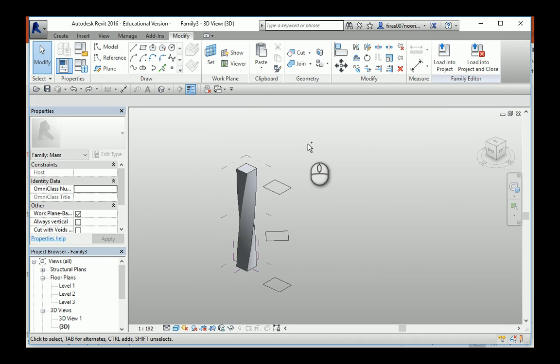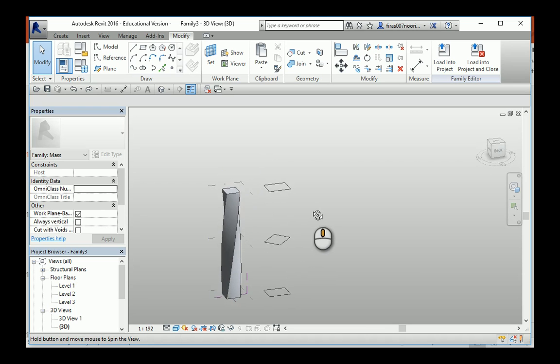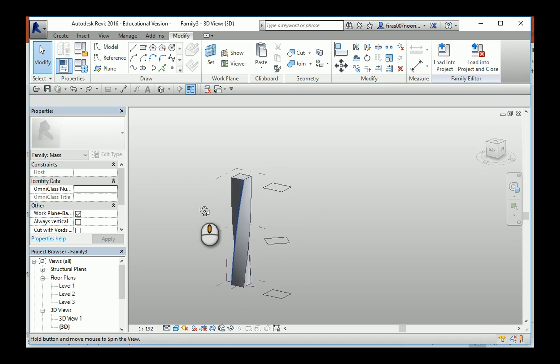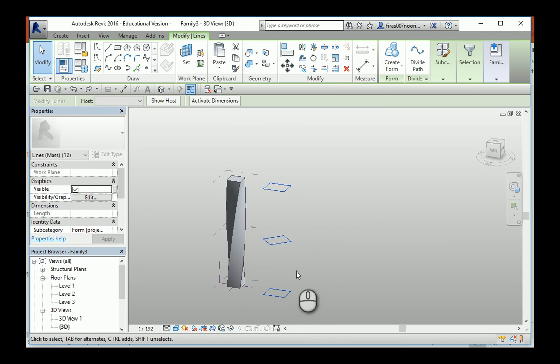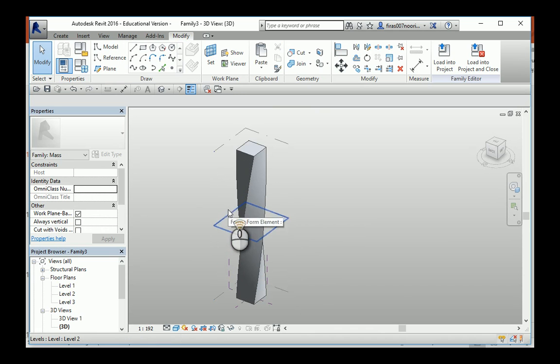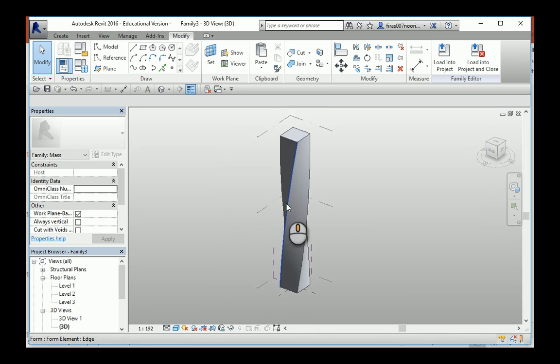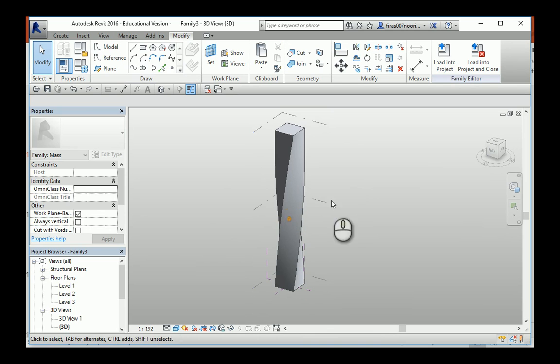So I would highly recommend that you do the extrude first based on the existence of a 3, and then you rotate, rather than just select one and then the second. That will make a line jump from here and then a line jump from here. Here it makes a smooth curve. So there are lots of small line segments here to create this curvature, rather than making those 3 straight edges a twist extrusion.